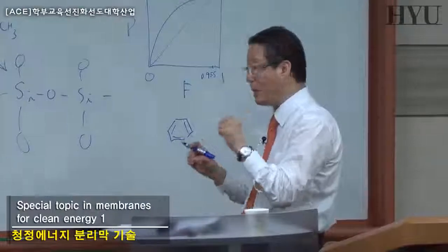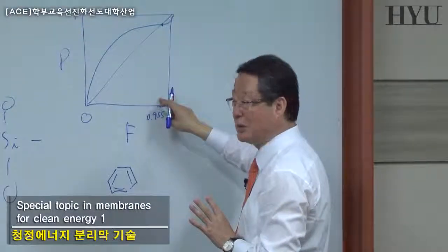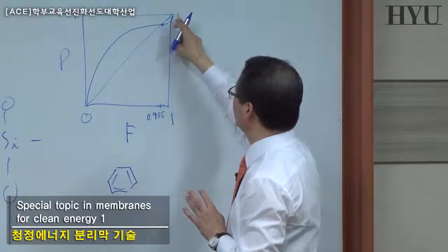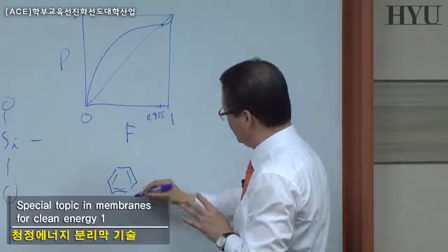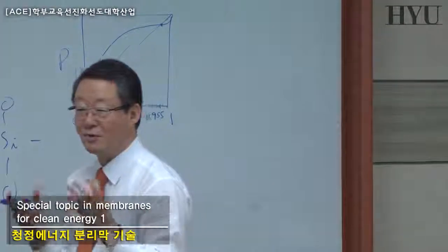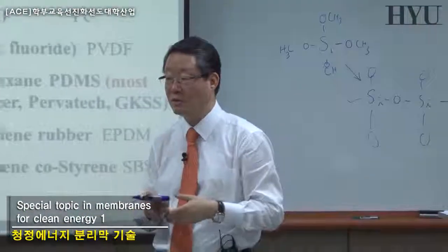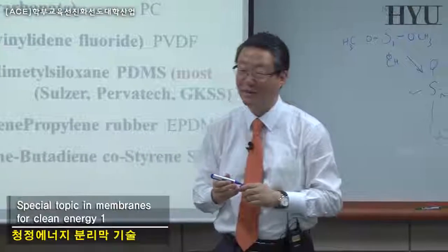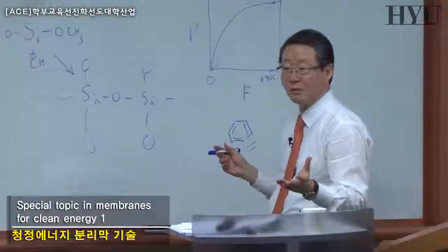So if you add a small amount of benzene in the aqueous ethanol solution at a high concentration, yes, you can break them and can go up to about absolute alcohol. However, you still can contain a little bit of benzene, and if you drink your benzene, what's going to happen? Although it's a small amount, it's carcinogenic, so it's not feasible.